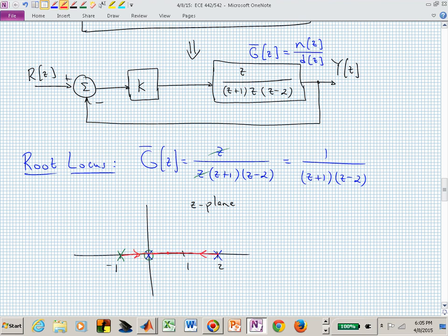So now you're focused on two poles and only two poles. What's the distance between those two poles? What's the linear distance? 3. They're going to meet halfway between that distance. So the one at 2 is going to move 1.5. The one at minus 1 is going to move 1.5 to the right, and they're going to meet at 1/2. Right?